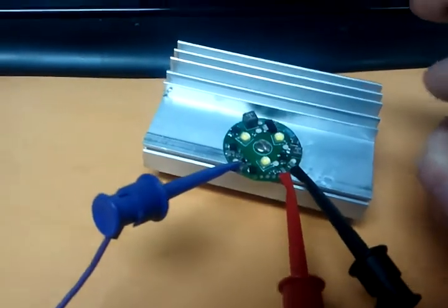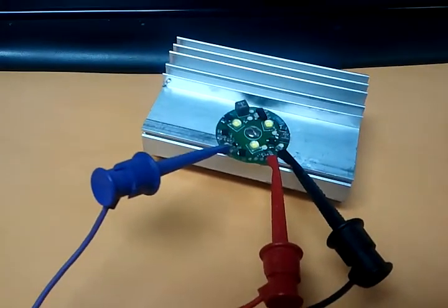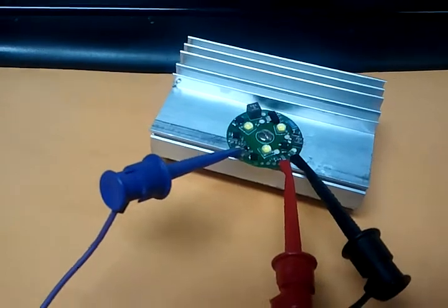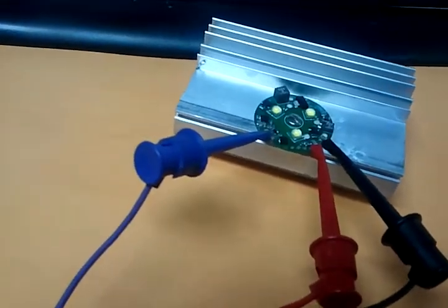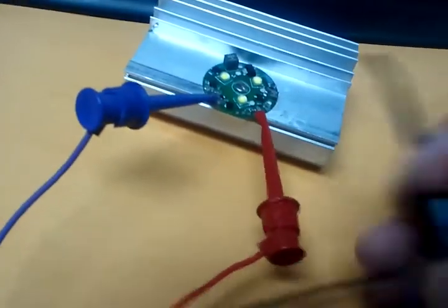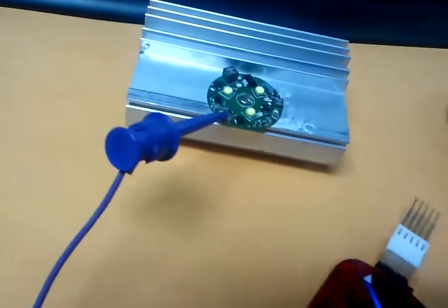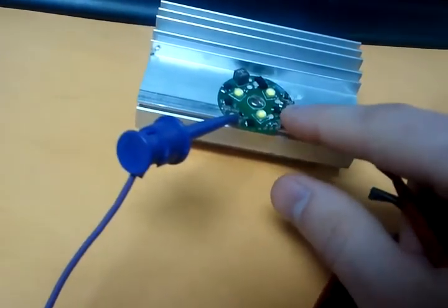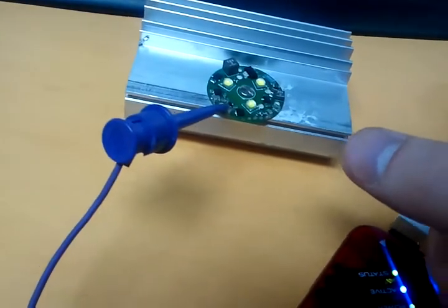There we go. So that's how you use the Mode Designer along with MPLAB in order to program new modes into the module. We could repeat that process with different modes, and it would be exactly the same sequence of events. Just remember, when you do program using the PICkit, disconnect your battery or your power from the module. You can do that either by removing the connections here or by simply taking out the battery and leaving the wires in place. Of course, that's fine too.